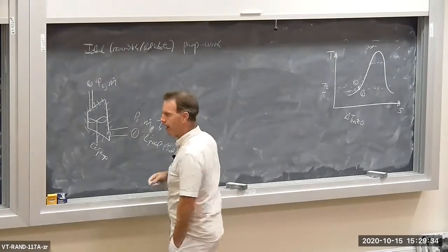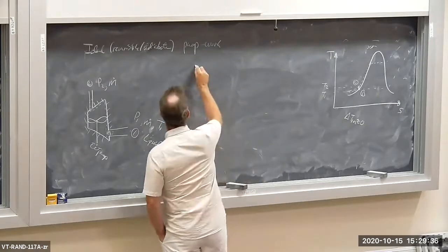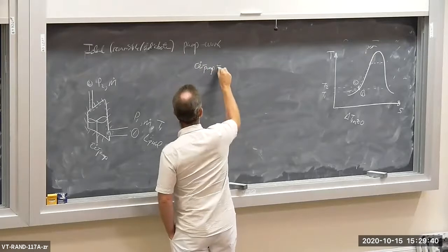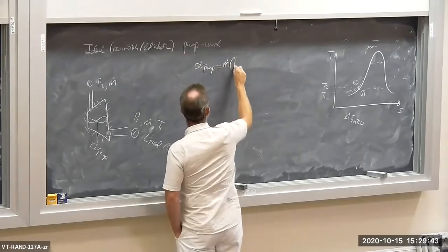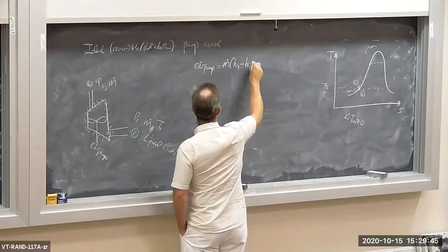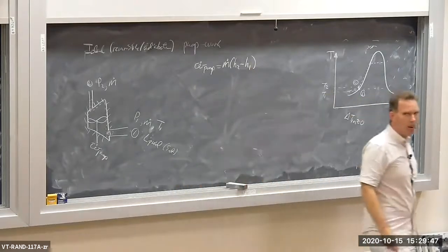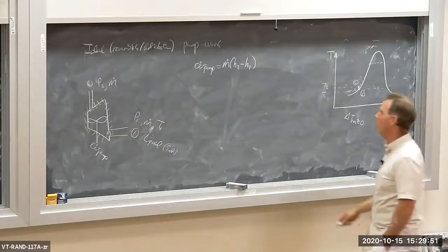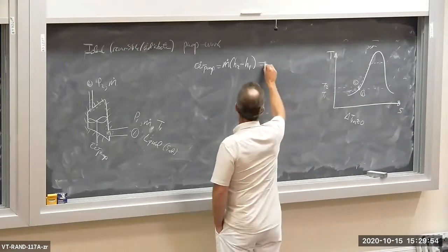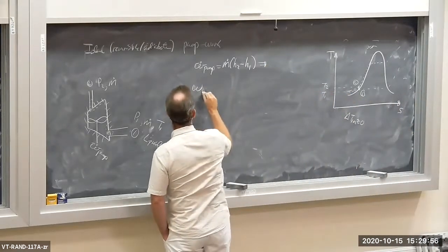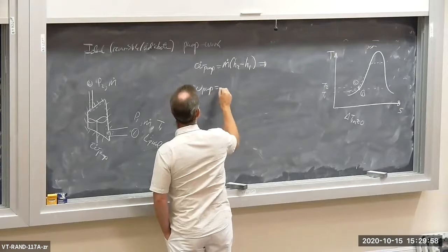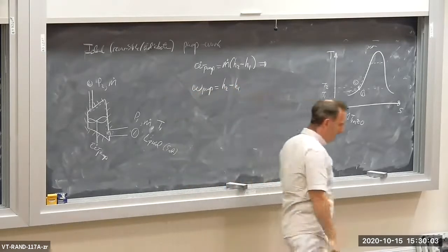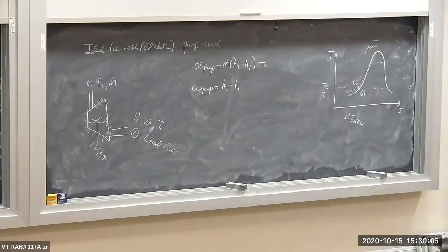We're going to get W dot pump is equal to M dot (H2 minus H1). That's going to be our pump power. Dividing through by M dot, we get the specific pump work is equal to H2 minus H1. Okay, that's not very surprising.